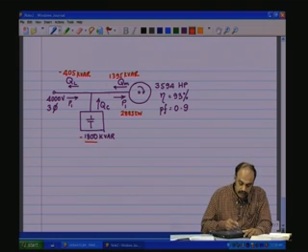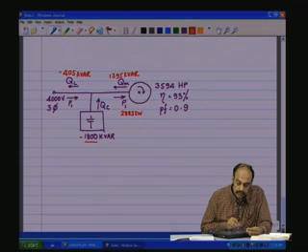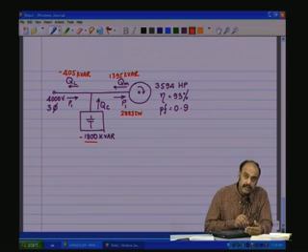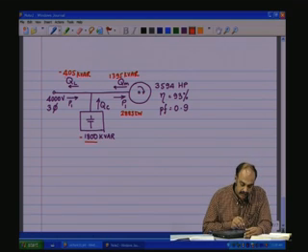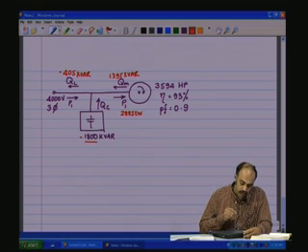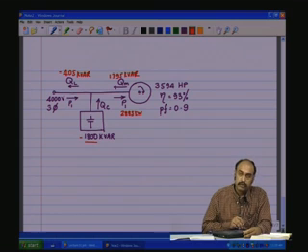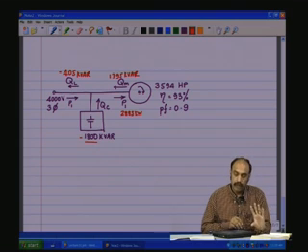So, the reactive component of the load alone would have been 1395, but because we have put this capacitance compensating network, the line side kVAR has now grossly reduced, and in fact it has gone leading. It has gone into the capacitive side as minus 405 kVAR. If we had put only 1395 kVAR rating capacitance here, that would perfectly cancel, and then the reactive component on the line side would be 0 and the line would be just giving you active power.